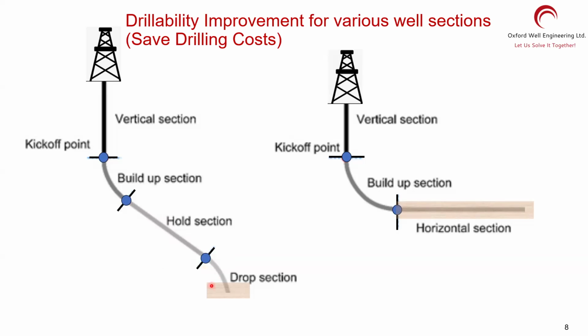This is engineering we are talking about. And same thing with the horizontal well. You need to land it. You need to be smart with it because you need to land it at a certain point. If you get it wrong and get it horizontal, it could be above the target or below the target, and then you did not hit the target. Then you have to sidetrack to get to the target. That goes into the cost. Very massive cost, actually. You have to re-drill the whole section or whatever. So those things you need to be aware of, and that can be a big thing on the drill cost.